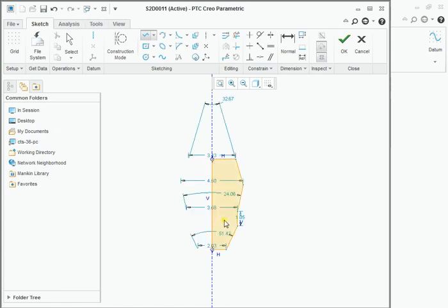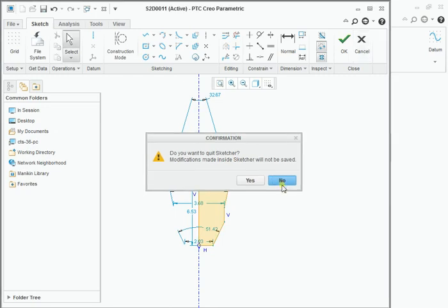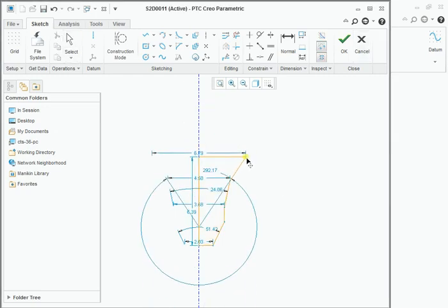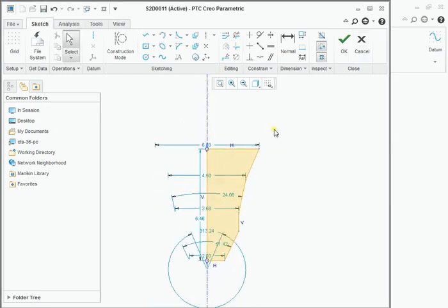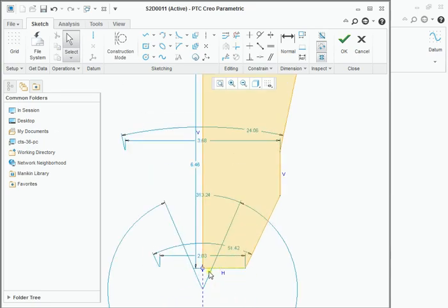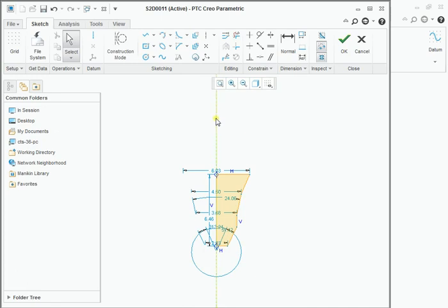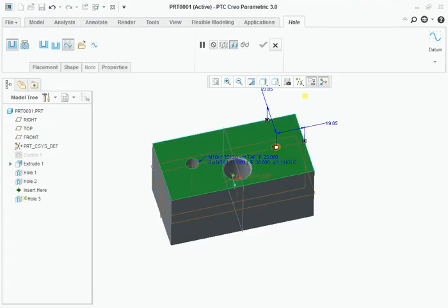For example, I am specifying it like this. Specify your dimensions, and for the end condition I am using the flat end. The profile must be a closed loop, and the center line is very important because the hole is a revolved cut feature. Click the check mark to accept this.